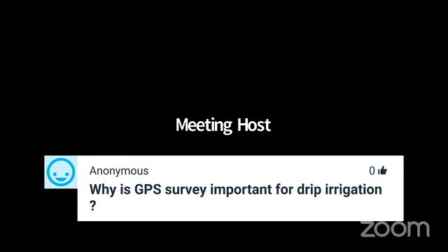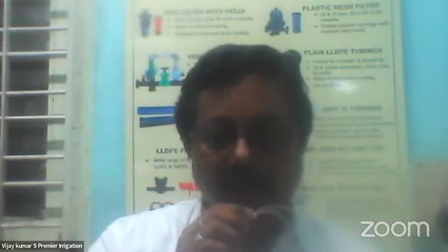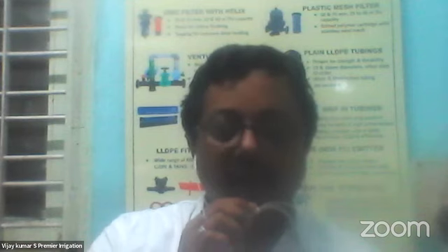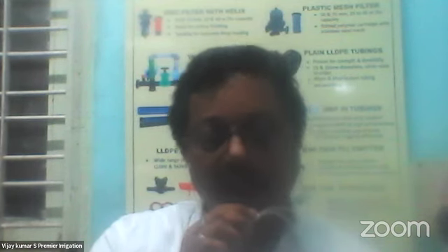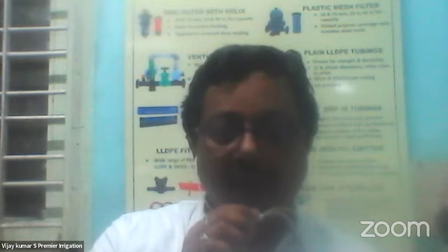Why is a GPS survey important for drip irrigation? See, the whole basic part of a drip irrigation system is that we start from the survey. We want to know how much area we want to irrigate, and then based on the area, I calculate the quantity of material for the drip irrigation lines and the filter unit and everything. So the survey forms the basic step before we actually carry out a hydraulic design and do the quotation.